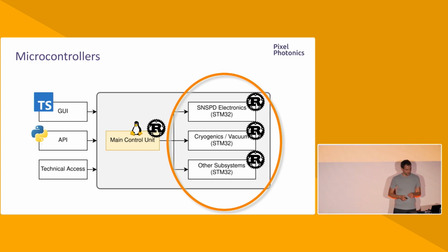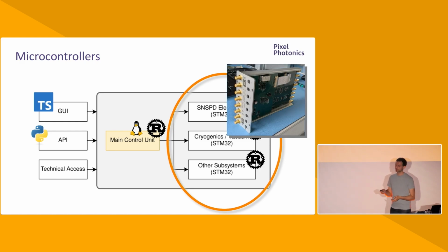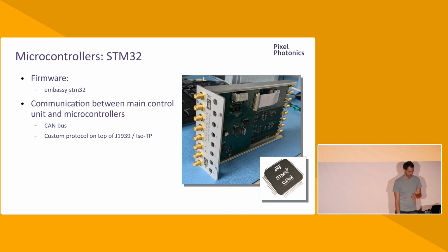Then going back to the system, we also have microcontrollers, as I mentioned in the beginning. So one of the systems here on the right may look like this. This is the driver electronics for our measurement chips, actually, for our sensor chips. In our case, this runs on STM32, and there's good support for this. No vendor support, but there's good community support from, for instance, the Embassy STM32 crate, which is very nice and well maintained, and offers support for a huge bunch of different STM chips.